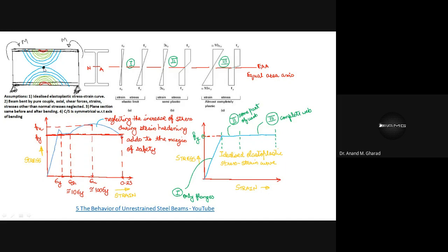At this very point, what happens? There is a development of hinge, and the property of this particular hinge is that even with the further increment of the load or the moment value, what will happen? There will be infinite rotation, because what will happen at this stage? The complete material will break with the further increment of the load or with the further increment of the moment.